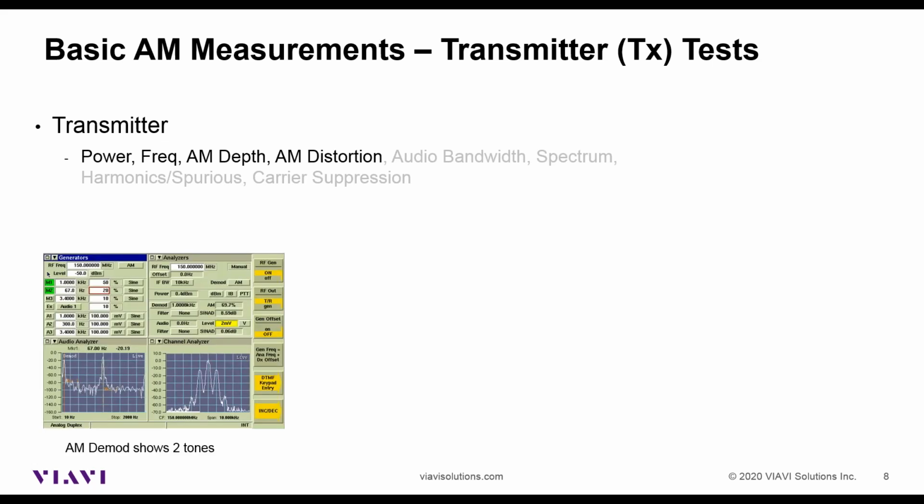So let's have a look at some measurements, and I'm going to do this just using the PowerPoint slide, and hopefully at the end, if we have a few minutes, I will show you something live on the AM radio I have here. So some of the things we might want to do is look at things like power, frequency or frequency error, the AM depth of modulation, and the AM distortion.